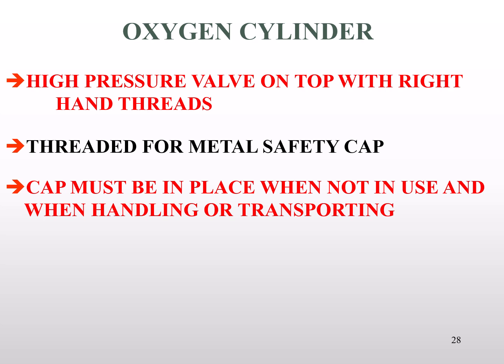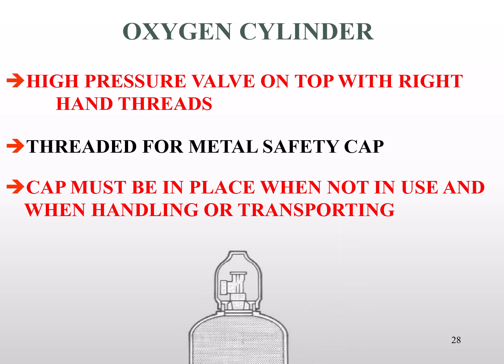Also, if you move an oxygen bottle, even if it's across the shop area, you should always put your safety cap on before the bottle gets transported. If the bottle were to fall over and knock that brass valve off, it could penetrate through several walls of the building before the pressure drops enough that the bottle slows down. Like I said earlier, they become an unguided missile.